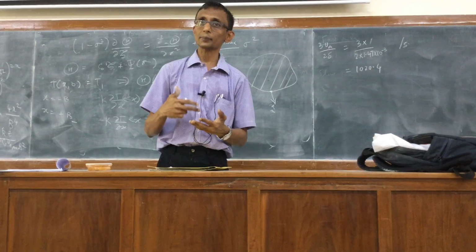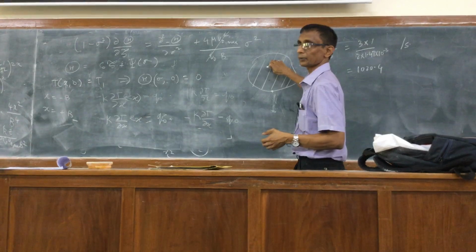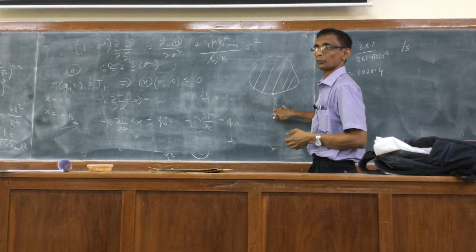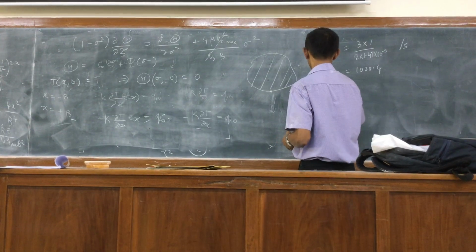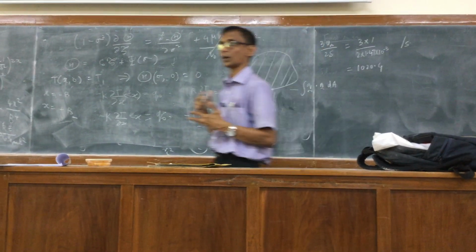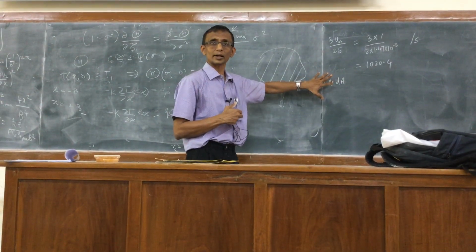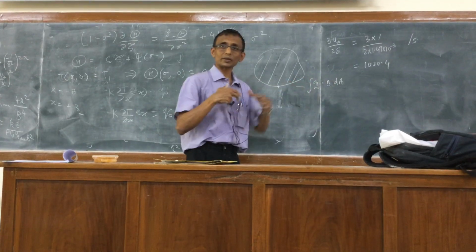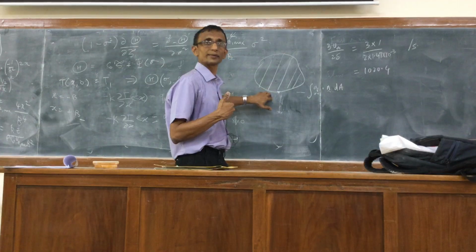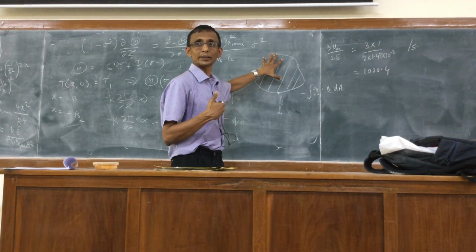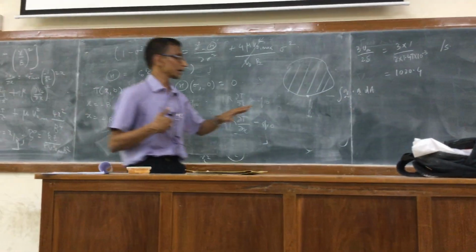Now here again the same principle applies. If I want to transfer heat to the body from outside by convection, then over the whole area it will be minus q dotted with n dA. The minus is coming in because traditionally, when you write minus k dT by dx for instance, q dot n will effectively correspond to the flux coming out of the body. So you have to put a minus, because heat coming into the body is to be treated as positive. So there is a sign condition already there. That is why the minus is used.